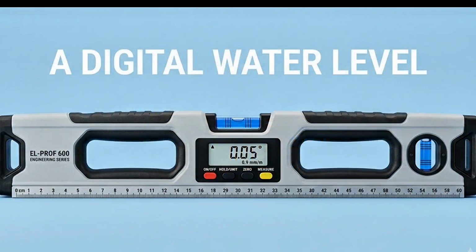A water level uses the principle that water naturally seeks the same level in connected tubes. It consists of a transparent hose partially filled with water. Builders use it to transfer level points between locations that cannot be seen directly from one another. It is inexpensive, accurate, and very useful on sites without advanced leveling equipment.